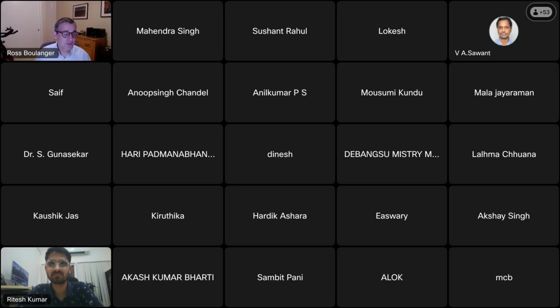So the variograms in the vertical direction are easy because you're going to have CPTs and there is lots of data. So you'll develop your vertical variograms, no problem. But the horizontal variograms are very complicated because you'll never have enough data to constrain both upstream and downstream, so X and Y in plan view. And they might not be stationary, in that you might think you're in the same geology, but the stream meandered more over here than it did over there, and you haven't picked it up in your exploration. So you may not be picking up a non-stationary feature.